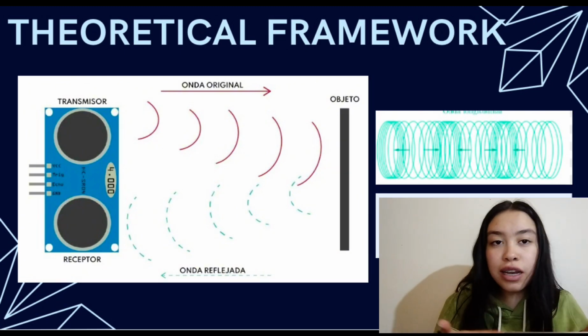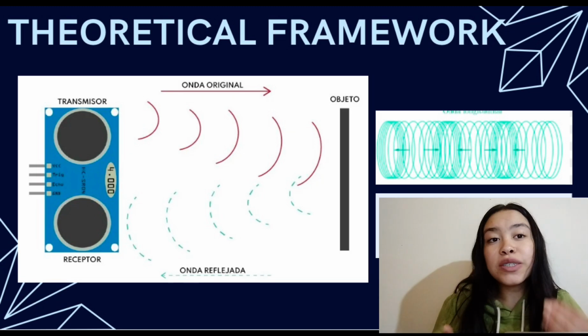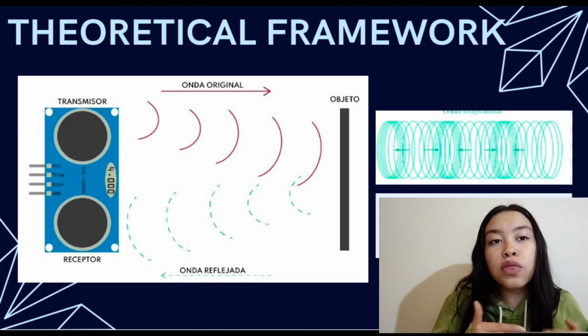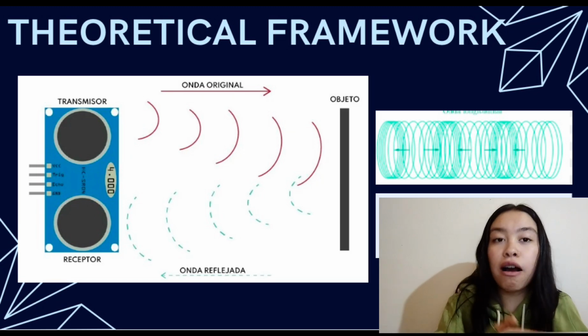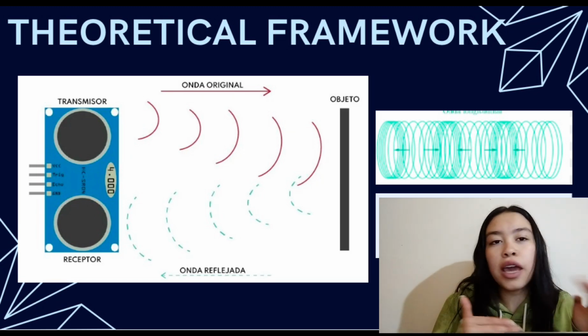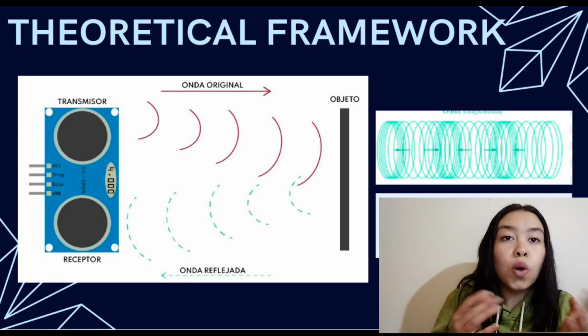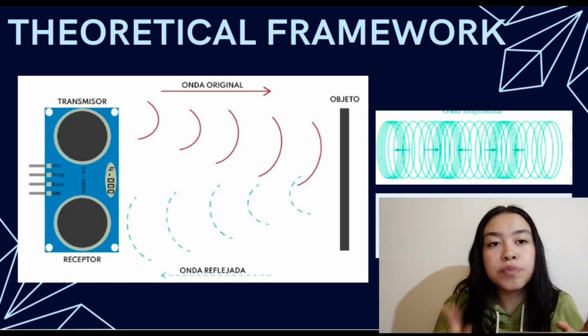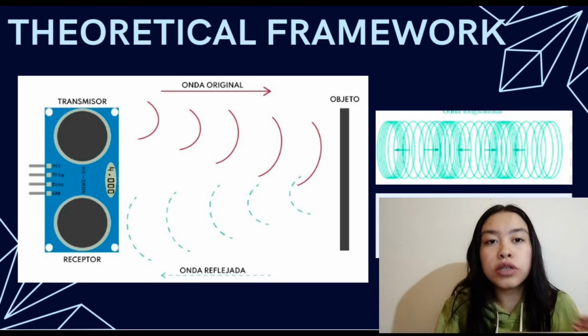The sensor generates an ultrasonic wave through a piezoelectric or similar transducer. This wave travels through the air or any gaseous or liquid medium until it reaches an object.